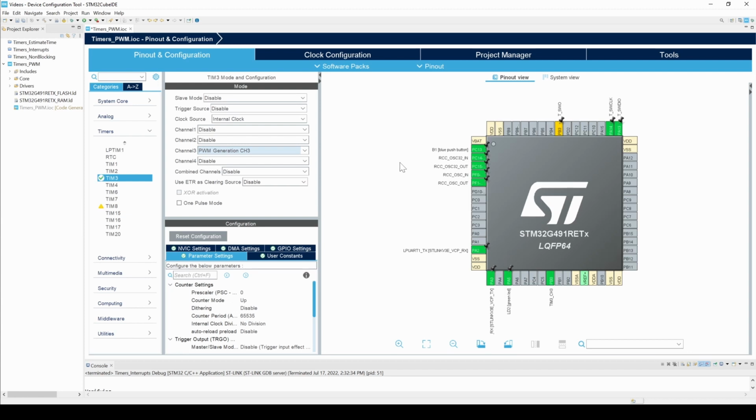Note that some pins on the STM32 have multiple timer channels assigned to them. For instance, when we chose Channel 3 of Timer 3, the IDE default selected pin PB0 in the bottom center. We do not want this. Therefore, we will reset this pin state and select our correct pin, pin PC8. Next, we can enter in our values for our prescaler and our auto reload register.